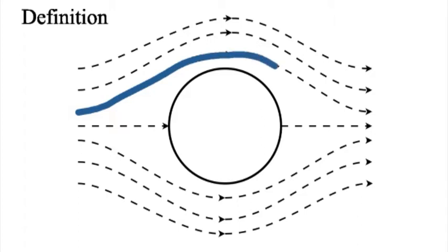However, it is easier to visualize if we move along with the body as opposed to moving with the flow. At every point along the particle's path, velocity is always tangent to this path. Since there is no normal component of the velocity along the path, mass cannot cross a streamline.